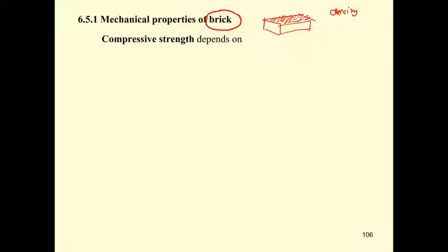Some of them you put into the water to measure the water absorption of the brick, and another one you put into the compression test, and then you measure the so-called compressive strength. Good brick with a good production process and good handling will have high compressive strength and high durability.